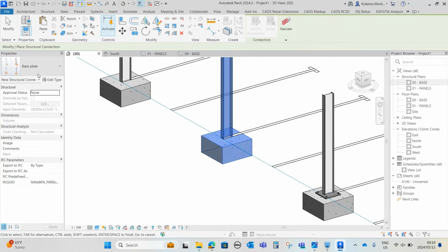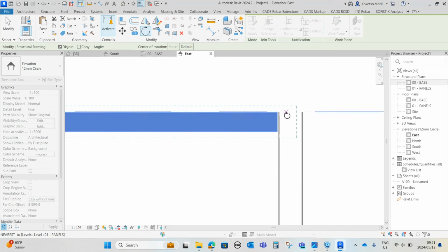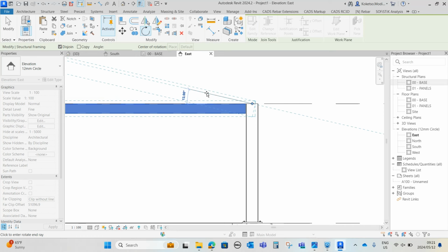And then from this moment, we're gonna draw our beam. So we're gonna take it to the left by 6,000 millimeters, but we're not gonna stop there. We're gonna select it and then we're gonna rotate, go to place, and then we're gonna place our insertion point from there, our rotation point from there, and then we're gonna rotate it upwards by, I think 10 degrees is fine.